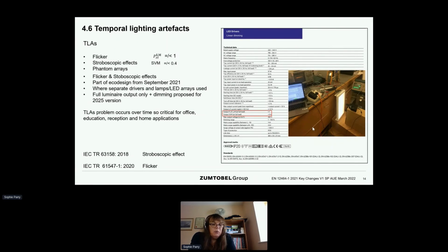And if you had a single luminaire and walked around it with your phone, the frequency of roll of those black lines would change, which is a little bit unusual because if something's flickering, it's flickering. The flicker value or frequency doesn't change as you walk around it with a phone. So don't think that getting your mobile phone out when you're looking at luminaires is going to give you anything reliable, because it won't. It has to be done proactively. If you're doing it proactively, this is how it should be done.